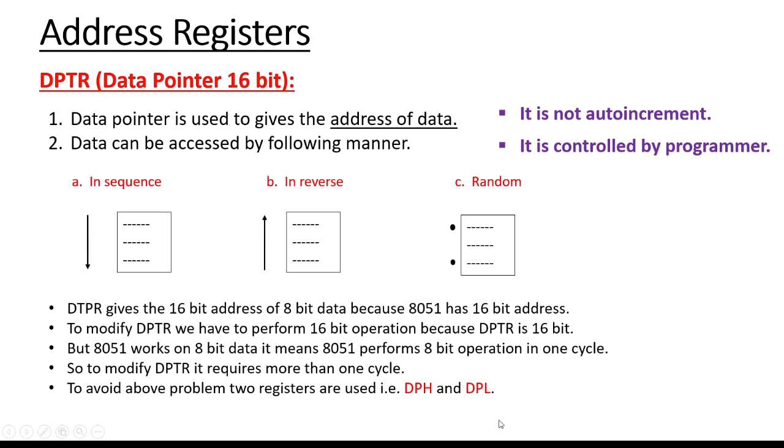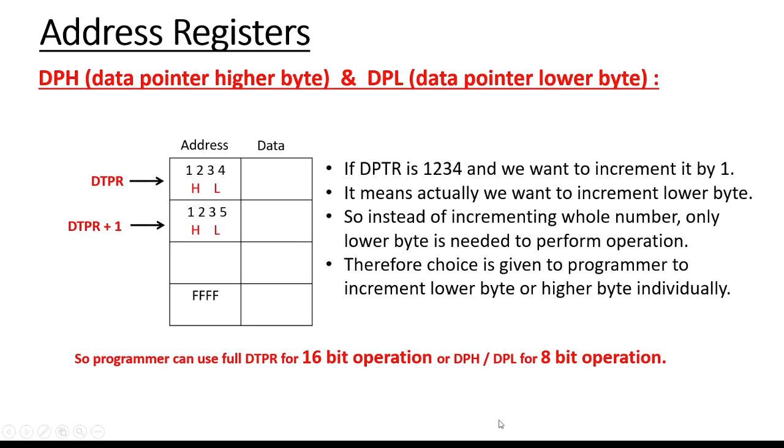DPTR is at the mercy of the program instruction and can be used as the 16-bit DPTR or as each individual 8-bit register by their individual names, DPH or DPL.